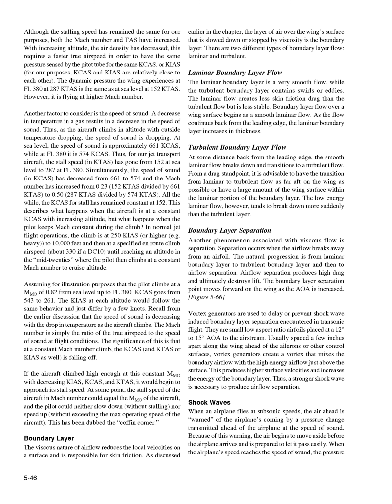Boundary layer separation. Another phenomenon associated with viscous flow is separation. Separation occurs when the airflow breaks away from an airfoil. The natural progression is from laminar boundary layer to turbulent boundary layer and then to airflow separation. Airflow separation produces high drag and ultimately destroys lift. The boundary layer separation point moves forward on the wing as the AOA is increased. Figure 5-66.